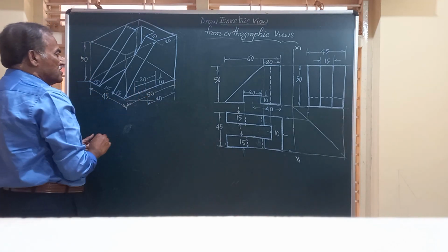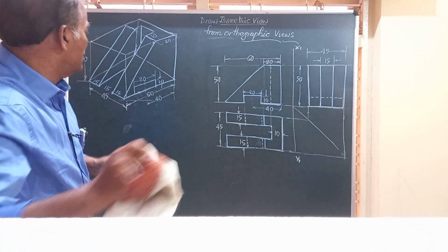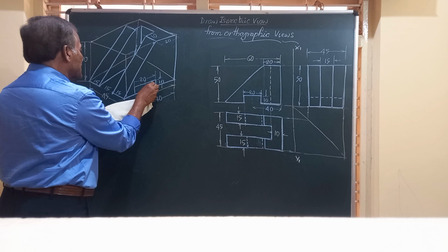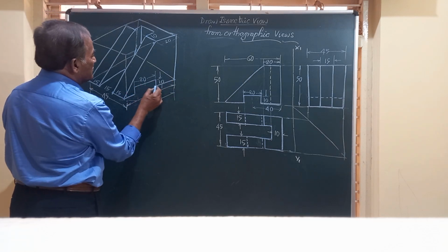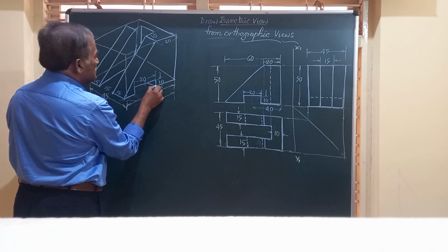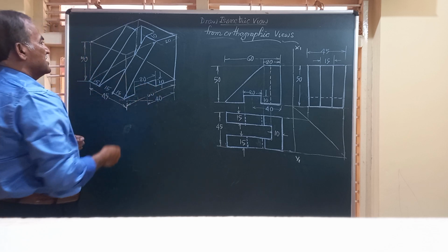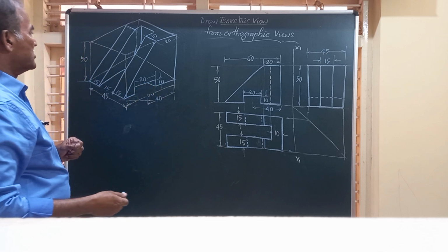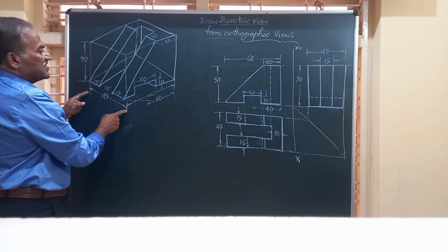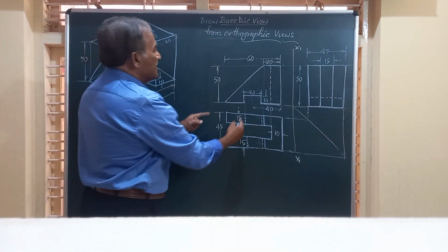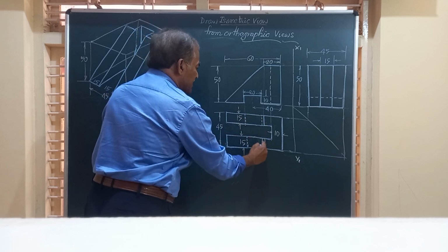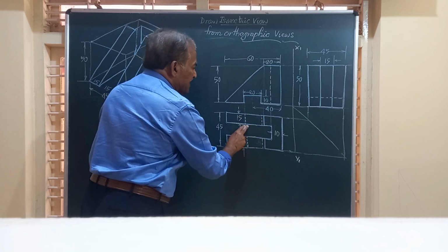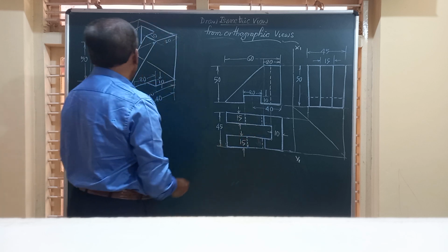So we have got this, friends. Once we have a slot there, we have to remove this line from there and draw a line parallel to this. This will indicate that there is a rectangular slot cut throughout the width of 45 millimeter, and that is shown by these two dotted lines. Dotted line, dotted line. There is no material here, and hence I have not shown anything there.